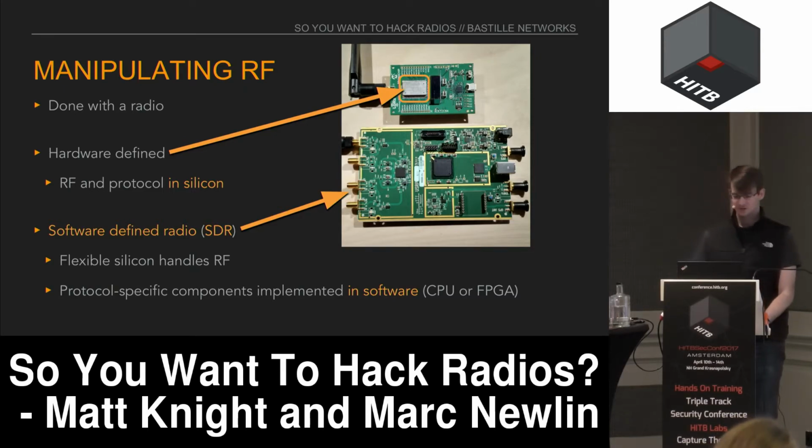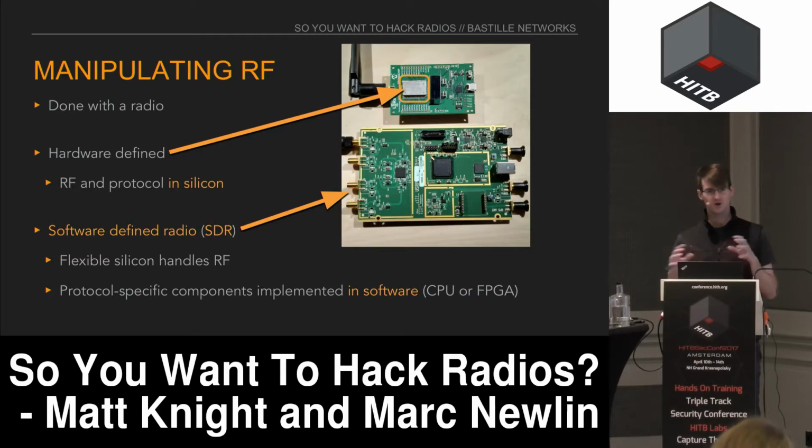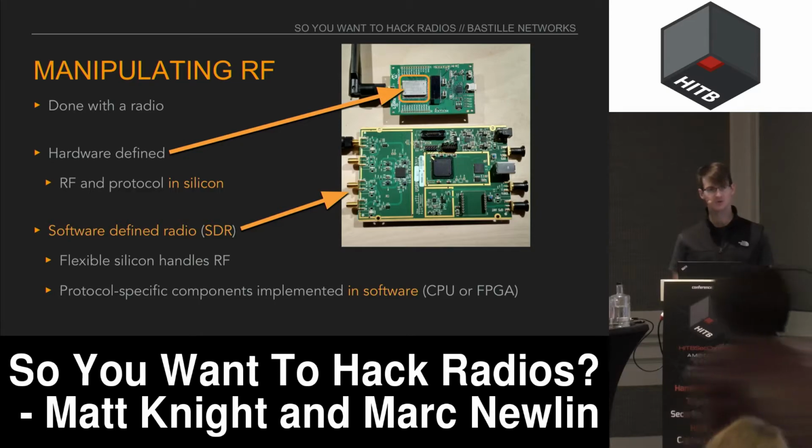You can manipulate RF by using a device called a radio. And as Mark mentioned, radios can either be hardware-defined, as is the case with the LoRa radio shown on top there, or they can be software-defined. With the hardware-defined radio, again, the features are baked into silicon and are not flexible. With software-defined radio, it's really just a way of grabbing raw radio information and passing it off to some sort of reprogrammable logic, whether it's software on a host or configuration of an FPGA.